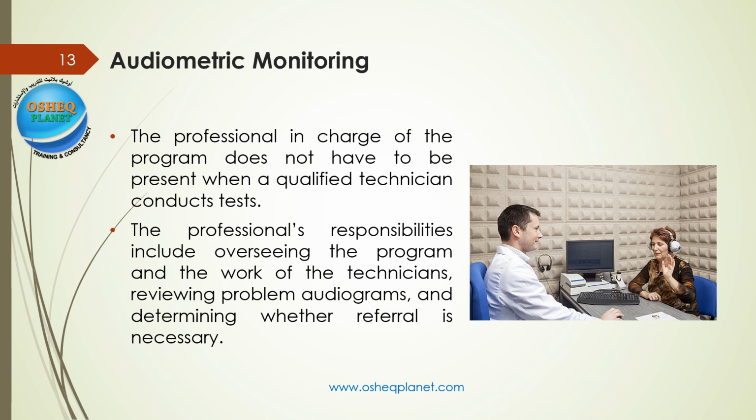In other words, the Occupational Safety and Health Department, for example, supervises the implementation of the noise measurements program in the facility and identifies the places where exposure appears higher than 85 decibels TWA, and then identifies the names of the workers in those places to submit them to the medical department to conduct the necessary measurements, audiogram.